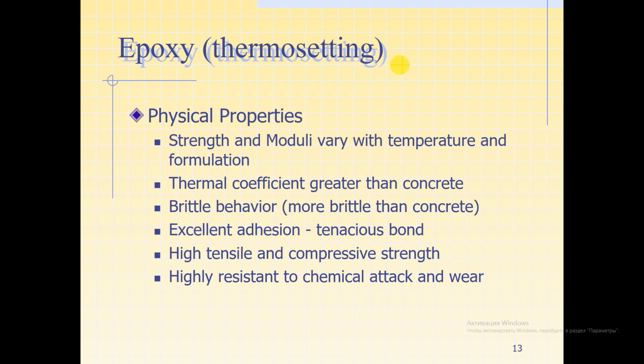They can be made flexible or rigid, transparent or opaque, colored, fast setting, or extremely slow setting. Epoxy adhesives are almost unmatched in heat and chemical resistance among common adhesives. In general, epoxy adhesives cured with heat will be more heat and chemical resistant than those cured at room temperature.